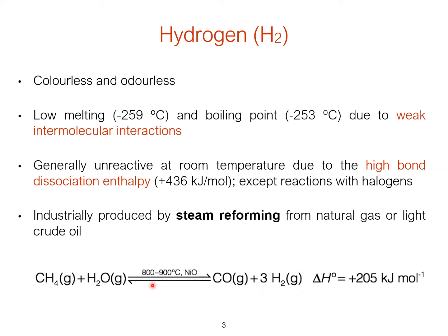It's done at such high temperatures, as you can see, nearly 1,000 degrees. If you remember back to when you were doing equilibrium chemistry in Introduction to Chemistry or whatever you did before, and Le Chatelier's principle, you'll notice here the enthalpy change of the reaction is endothermic, so it takes in heat, and the principle was if you apply an external factor to the equilibrium, it will shift to minimize this change. So we do it at very high temperatures because then this favors syngas production.